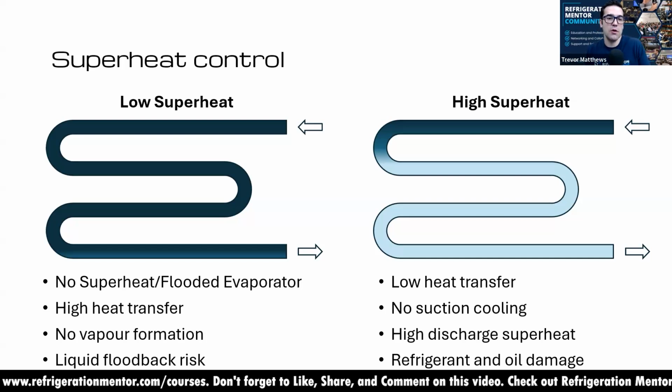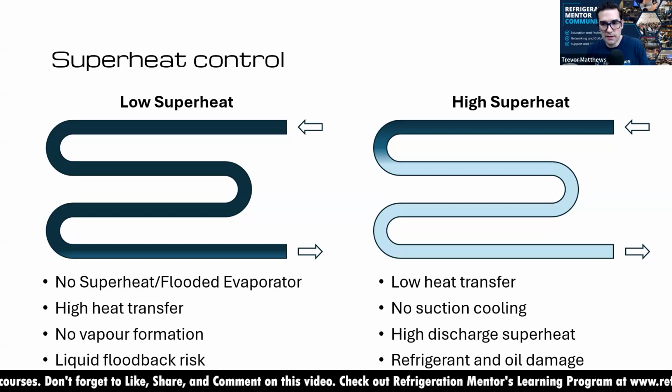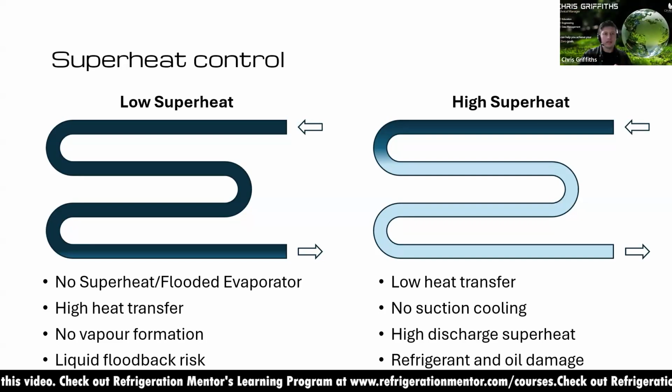Could that affect the temperature of a case, if you had low superheat and flooding? Could it increase the temperature, or would it drop the case temperature? Can you elaborate on that too, when the coil that is supposed to boil off is all liquid in there? I've not encountered a lack of duty from it, because you are picking up so much heat. I suppose the only alternative would be if it's flooding through at such a high velocity that it doesn't have time to actually pick up the heat. It's unlikely to happen in a system like this, in my opinion.